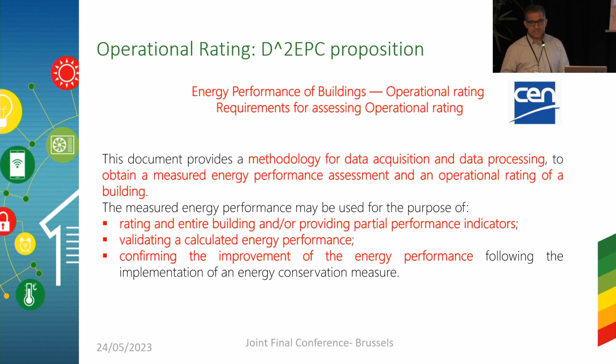And as a summary of the scope of the standard shown in this slide, we wish to provide methodologies for data acquisition and data processing in order to obtain measured energy performance assessment and operational rating of buildings. So this is the main scope of the standard. And the measured energy performance can be used for 3 different purposes, as we define them in the description of the standard: to rate the entire building or to provide partial performance indicators.